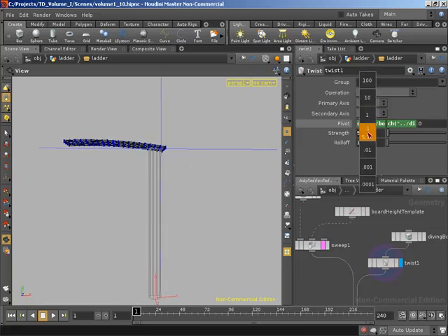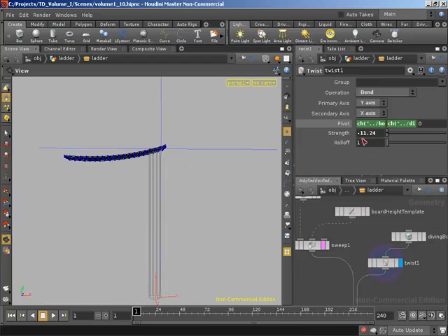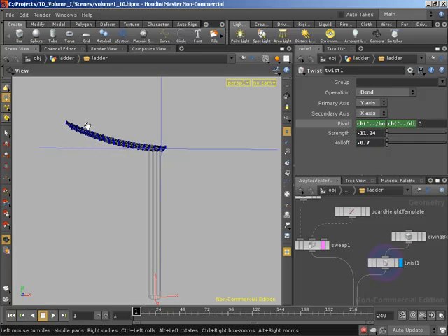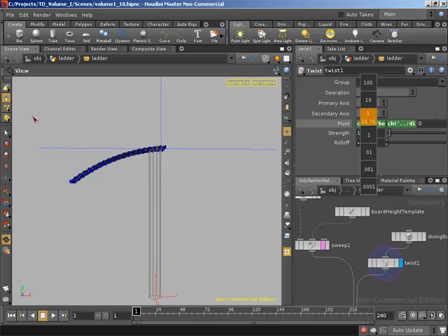We still haven't quite got it. If we start looking at this bend, it still looks really weird. We're going to change this roll-off value so that we can get a much nicer roll-off. So I'm going to start decreasing this, and I'm going to decrease to negative 0.7. You can see the effect that was having on the bend, pushing us further and further back here. So now, very nice. We get the bend as we'd like.